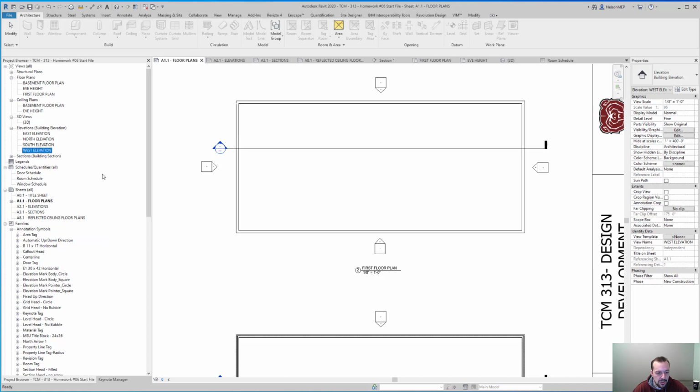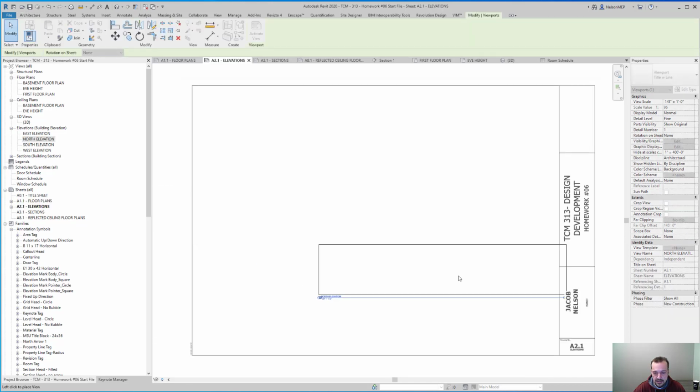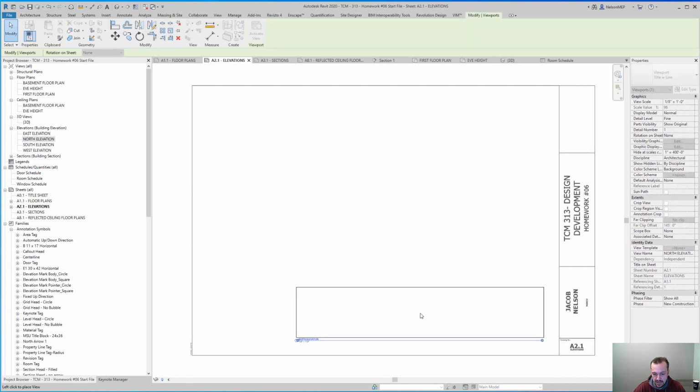Okay, so the easiest way to put this on here is we want to put them in order. The way Revit works, when I drag one over, it assigns 1 to it. The next view that comes in is 2, the next view 3, and so on. And so if we look at a grading sheet, the first detail 1 is north elevation. So I will drag my north elevation into the elevation sheet. I'll be sure to place it under here.